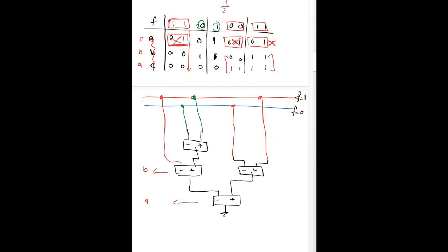So what we have done is we have removed 2 NMOS from here, 2 NMOS from here, and also 2 NMOS from here. So we are left with NMOSes, 1, 2, 3, 4. We have a total of 8 NMOS now, instead of the 14 we had. And similarly we have PMOS in a latch. These are 2 PMOS. In total we have 10 gates.